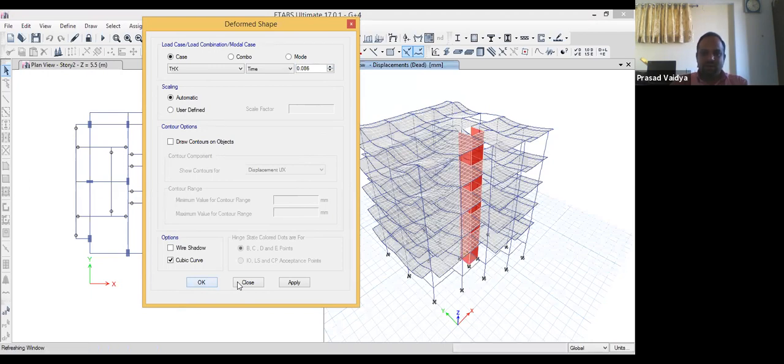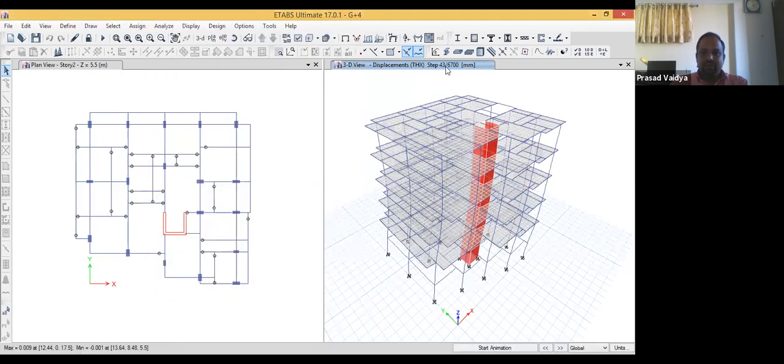Now I'm just refreshing it. That is the deformation shape. You can see we have put 6,700 time steps, and out of that, these are the results of the 43rd time step. Likewise, you can get the history of any response quantity. For example, the response quantity can be deformation of any node. If you choose a single node and want the displacement time history of that node, that is possible. What you will get is 6,700 displacement results for a single node.